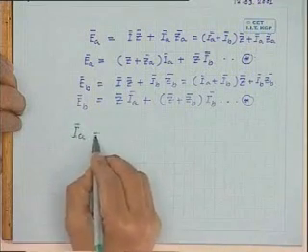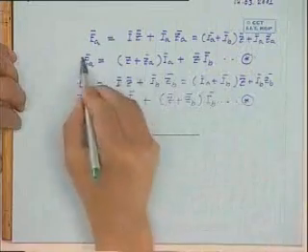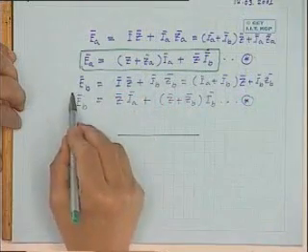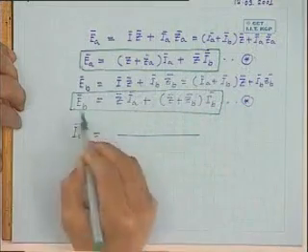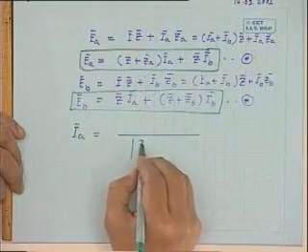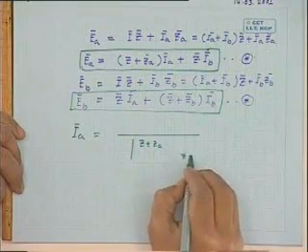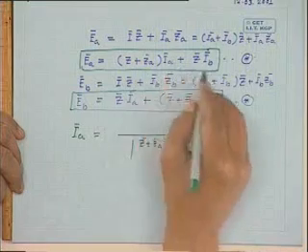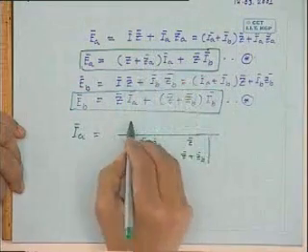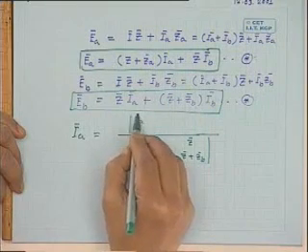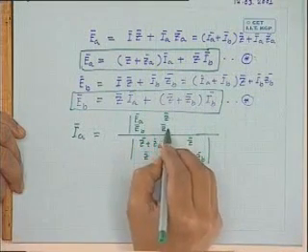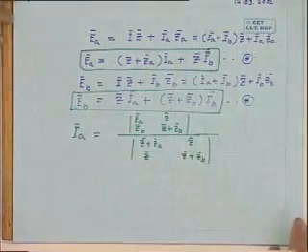Two unknowns, two equations. So IA bar will be equal to the impedance matrix with Z plus ZA here, and Z plus ZB here, all bar, and Z bar in the off-diagonal positions. The first column is replaced by the voltages when you are trying to calculate this one, and this will be Z bar plus ZB bar. I will be doing it very quickly, these are very simple things.